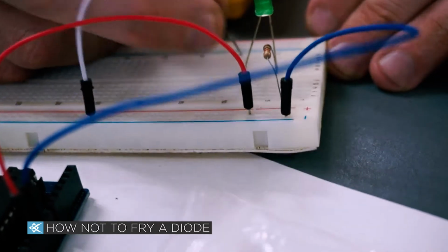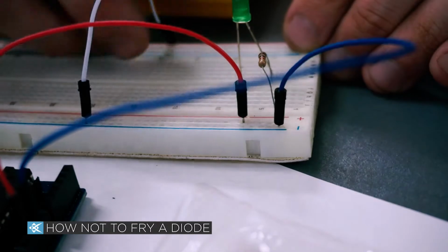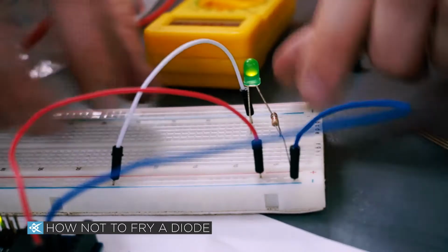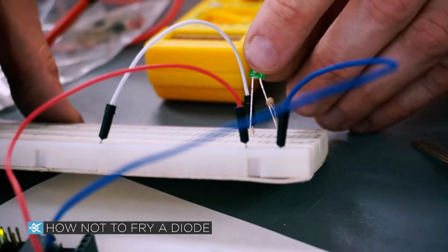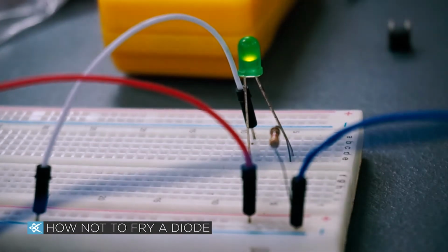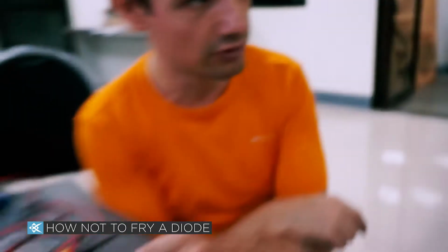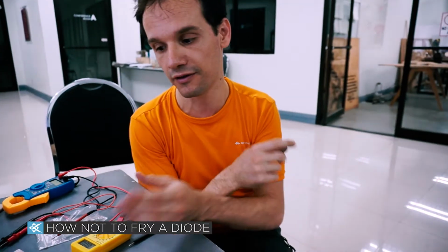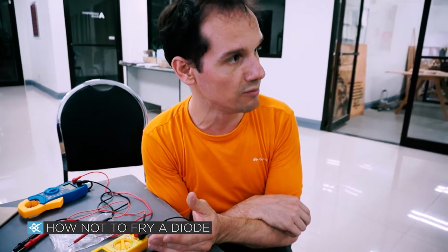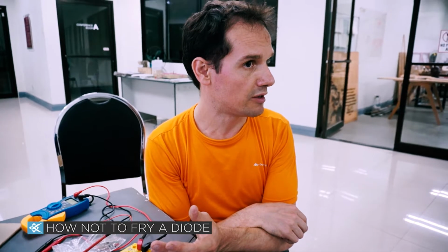Either it's the other way around, which is possible, in which case I got it wrong, or maybe the thing is already fried. There you go, it was the wrong way around. And it lights up. You can see it's pretty dim, and that's to be expected because we said we were going to use a 200 ohm resistor, but I put a 1000 ohm resistor because I didn't have a 200 ohm resistor. So I actually have 5 times less current in there than I wanted originally. Instead of the 20 milliamps that I was calculating, roughly, divide that by 5.